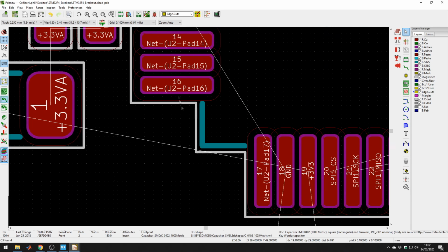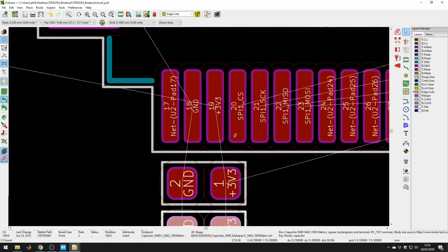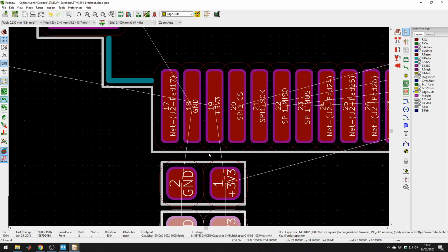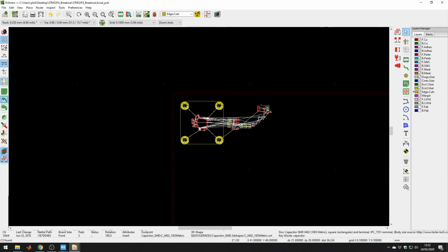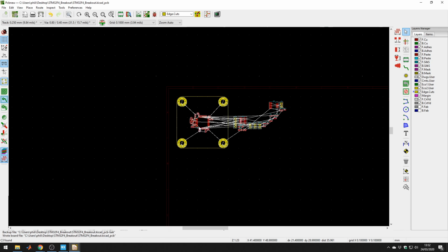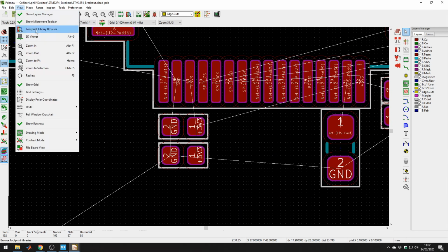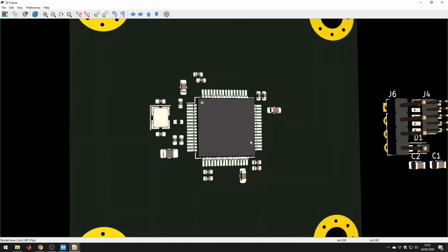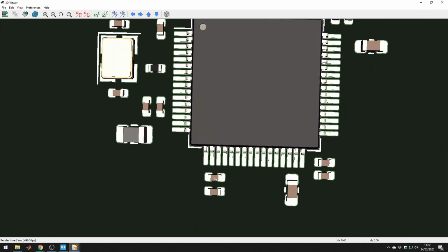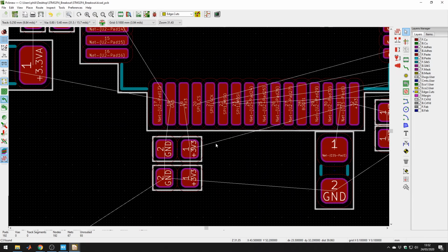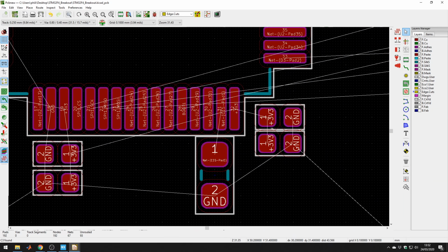Now you notice these distances here, you can go ahead and measure, this is 0.2 millimeters. Let's be honest, it looks huge here, but if you zoom out, this will probably be the real size of the board. So it's purely aesthetic. If we go to view, we can see how the component placement will be. This looks sufficiently close to the pins. Couple millimeters max. If possible, as close as possible, you want these decoupling capacitors to be.